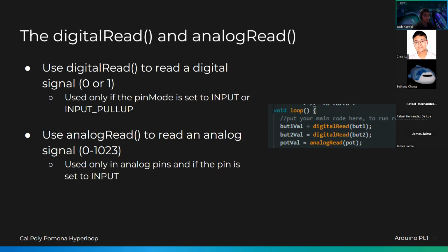That way you invert the logic so that when the Hall sensor detects a magnet, the pin can read that 0 happened, versus not knowing. Because if you use normal input, since the default state is 0 already, if you put a 0 in the input, nothing will change, right? That's why it's there for those kinds of circumstances.